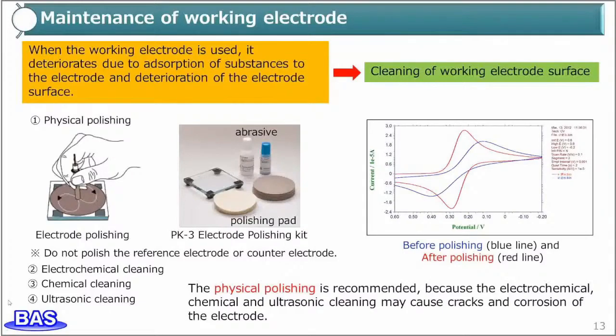Electrochemical cleaning, chemical cleaning, and ultrasonic cleaning may cause cracks and corrosion of the electrode, so we basically recommend physical polishing. BAS can offer the polishing kit as the PK3 electrode polishing kit.